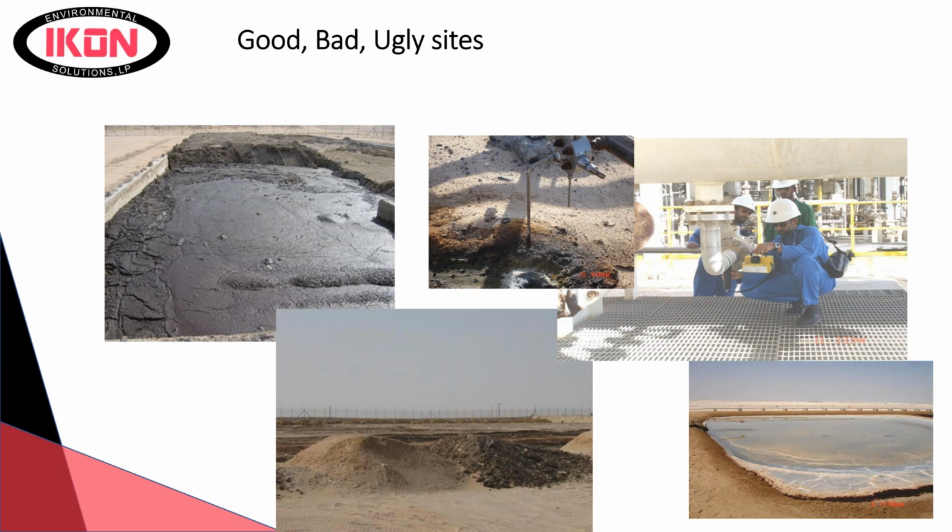They actually had a pretty good practice. We were just handling all this waste and had to do the closeout surveys for them to decommission their license. And we kept finding this, and we finally found out it was a city water line prior to water treatment that had been leaking for 10 years. And wherever they were pulling the groundwater up from just had dissolved uranium in it. And it created this kind of NORM plume in a ditch out front of their facility.